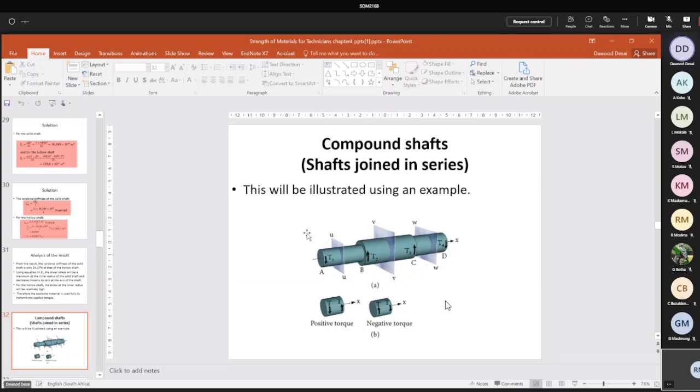Remember we said clockwise is positive torque, anti-clockwise is negative torque. You put your hand at the section, consider everything to the left-hand side of the section for the resultant torque. Any torques that pass through the border of the hand vanish. Same rules as yesterday, yeah? Exactly the same thing.